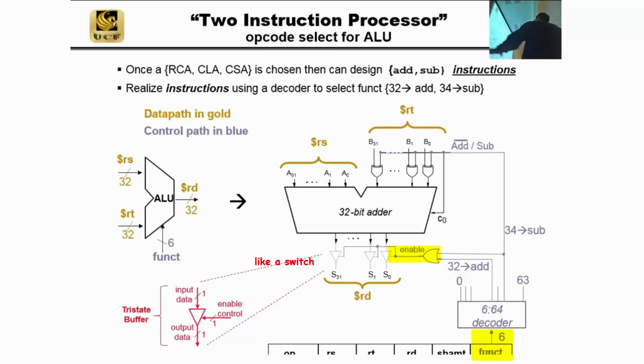There's going to be other times, right? I didn't draw all this because it's getting too much, right? But there's going to be other times the multiplier has an output that goes to RD, and other times SLL goes to RD, and other times shift right goes to RD. So who gets to talk so that we don't have this situation that one guy says a 0, another guy says a 1? You're going to say, well, why are they all computing these different things? Well, they may not be even computing.